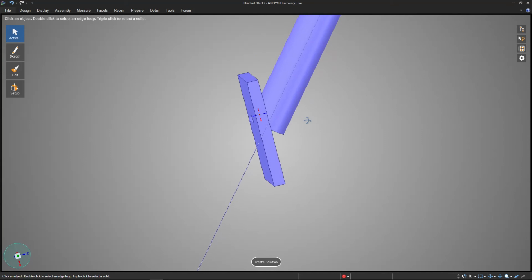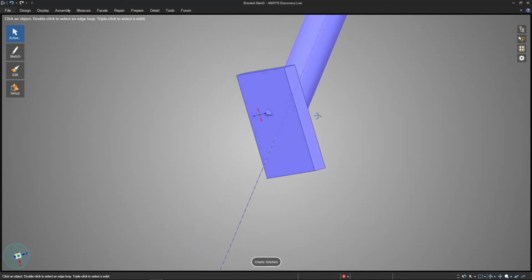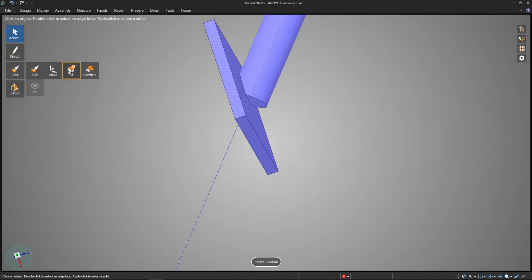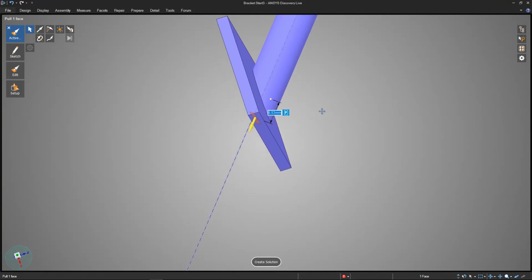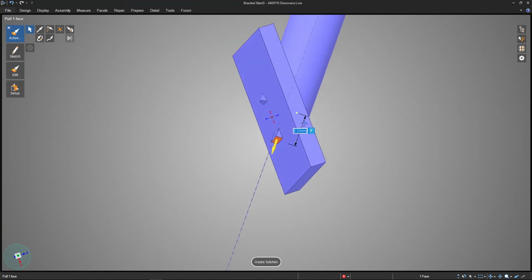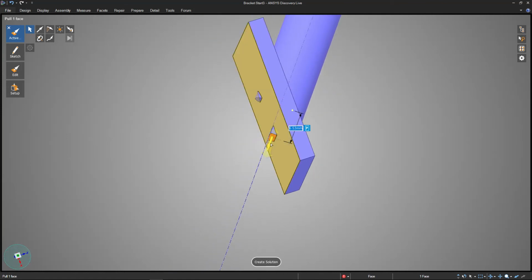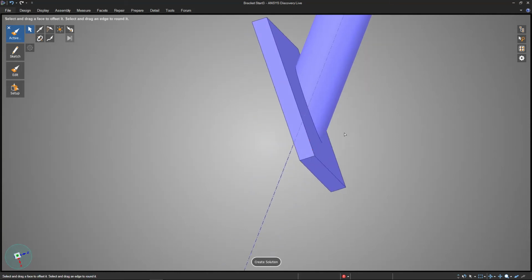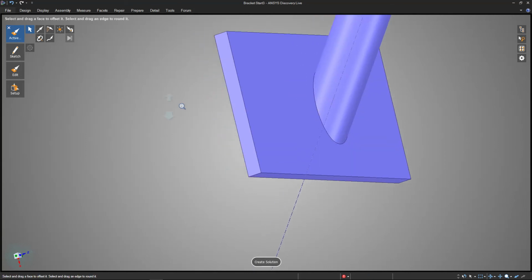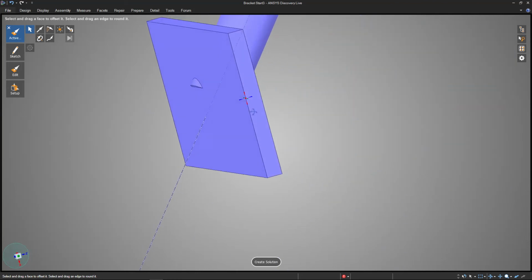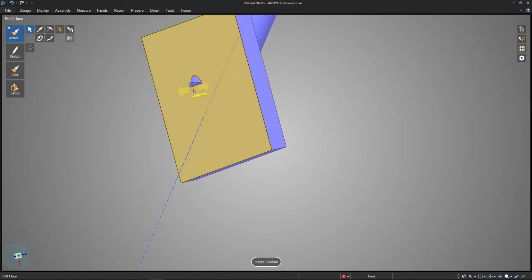Now when we try to move some stuff back and forth, we should get a slightly better result here. So let's again use the pull tool, select this face, and see what happens when we pull this down closer. So there it looks like it's now treating it as one whole shape, and I can get that to hide inside. You see it's already making it a nice circle on the inside here. And on the back, I've still got that little protrusion, so I'm going to push that inside the solid object here to get rid of it. Let me grab this flat face and push that back.